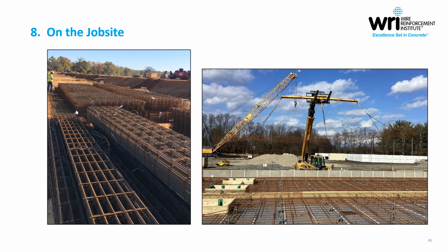Now, from the contractor's perspective, it's essentially an assembly line approach. The welded wire reinforcement detailer has already provided the answer key for the puzzle that has to be put together. They've illustrated, so to speak, the kit of parts that needs to go together. The contractor then will set up their work areas to facilitate the most efficient and timely installation of those puzzle pieces. So here the photo on the left shows a staging area.